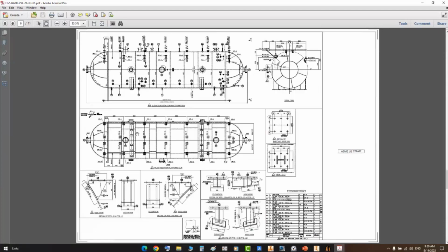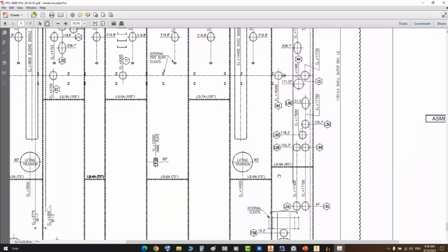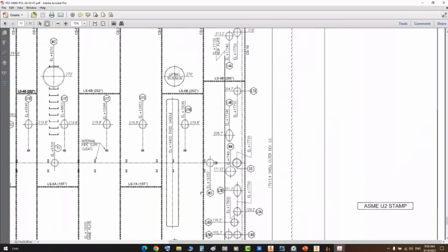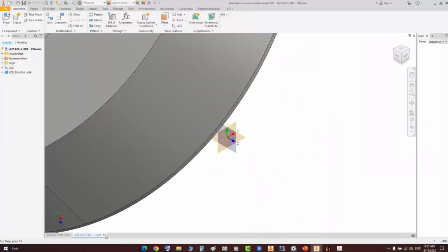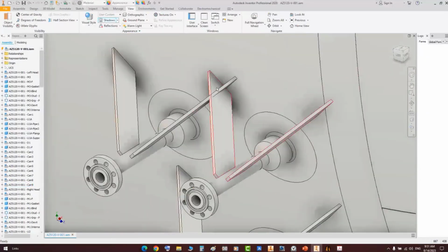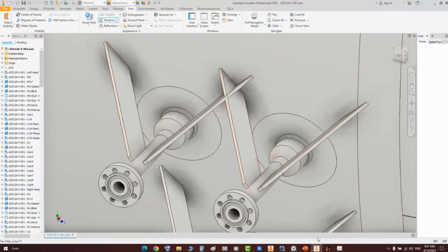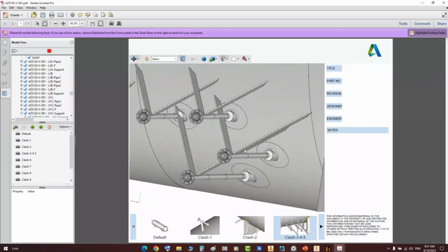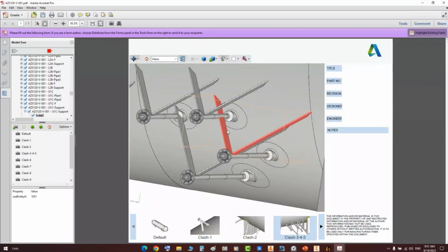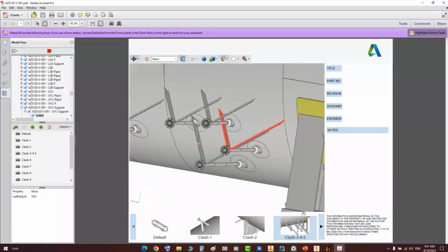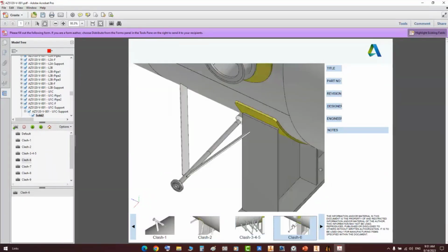And let's come down to the sheet metal development. And here on this drawing, no indication for the stiffening ribs of the nozzles. But here on the 3D PDF model or on the 3D model in Autodesk Inventor, you can detect that easily from the 3D model, like those stiffening ribs. Here you have a clash between them. But if you would like to send something to your client to discuss with him to change some locations, some orientations, or change the rib contact angle or the location of the rib, something like that, you can do it easily from the 3D model.